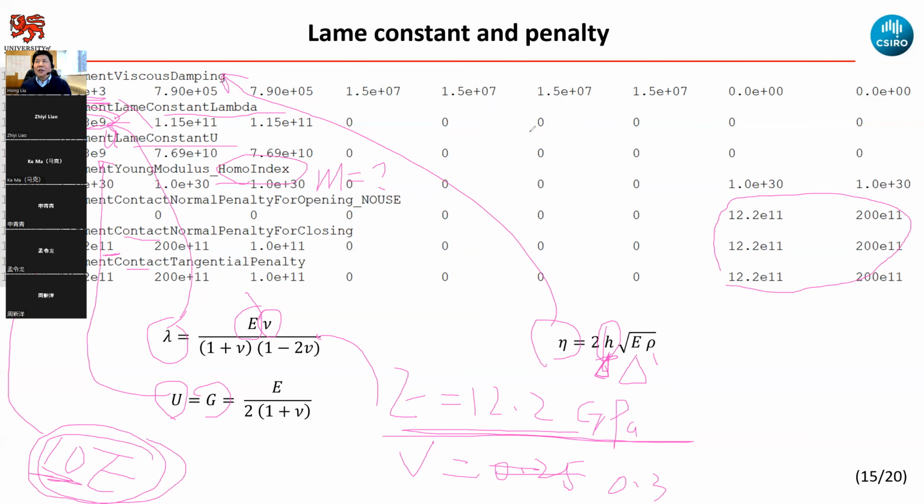We could consider the case where an element does not fail, but we still have the cohesive element inserted between the triangle elements. If it does not fail, you need to make sure it represents continuous behavior.